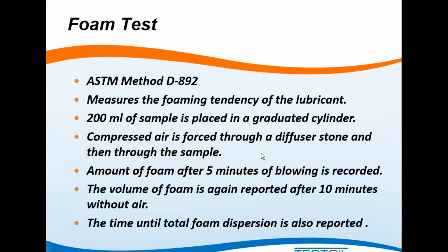And you want to consider that perhaps the dissipation time is what we're really interested in. If the oil is able to pull in air and then get rid of it, we're probably not going to have too much of a foam issue, at least in regards to the lubricant itself. Many years ago, I went to a seminar, and there was a study where they were talking about how many foam issues are really caused by lubricants, and it was a lot lower than I thought. A lot of times, foaming tends to be more mechanical in nature than a problem with the lubricant.